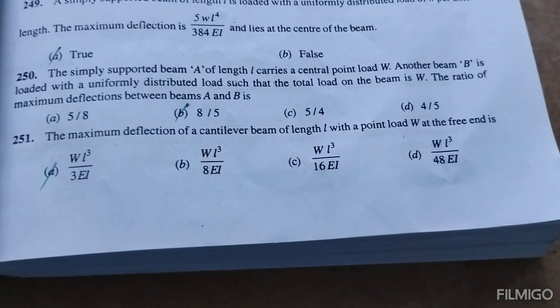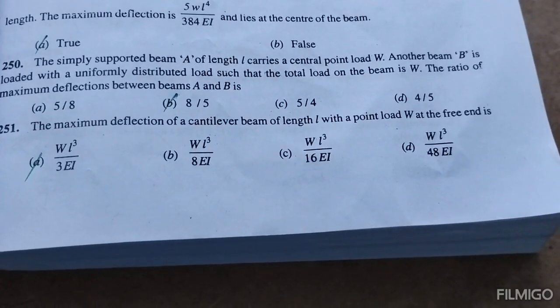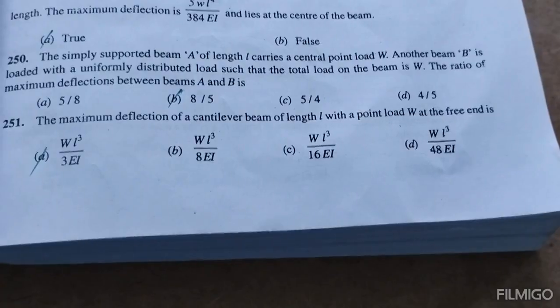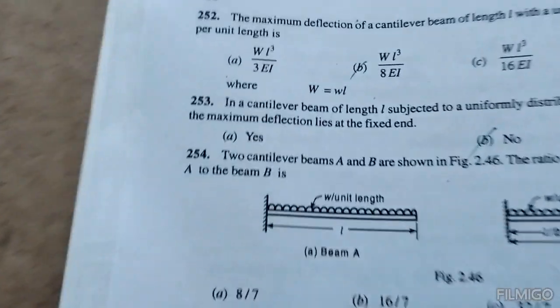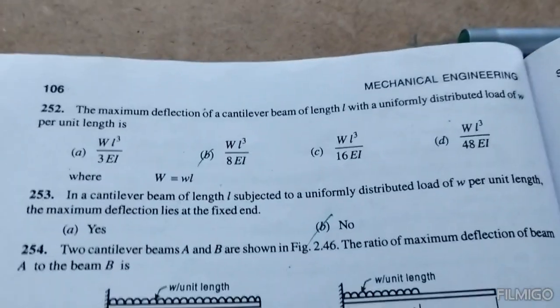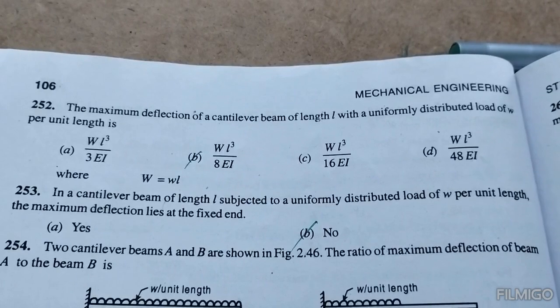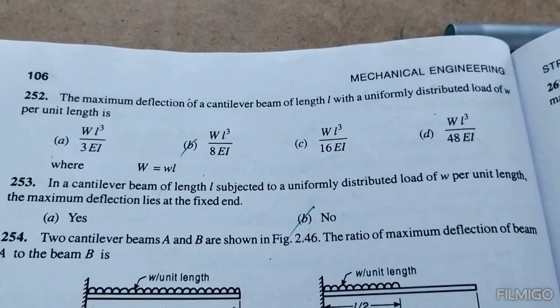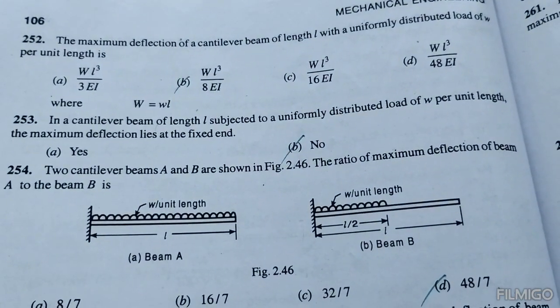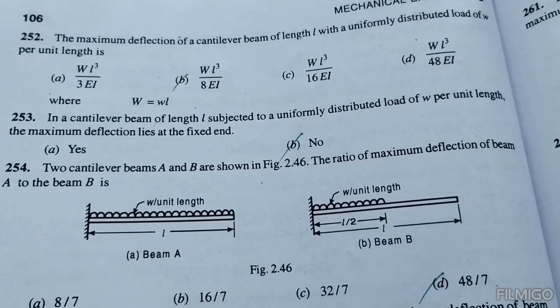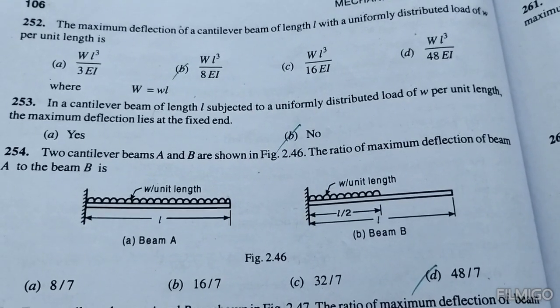The maximum deflection of a cantilever beam of length L with point load W at the free end is WL cube by 3EI. The maximum deflection of a cantilever beam of length L with uniformly distributed load W per unit length is WL cube by 8EI. In a cantilever beam of length L subjected to uniformly distributed load W per unit length, the maximum